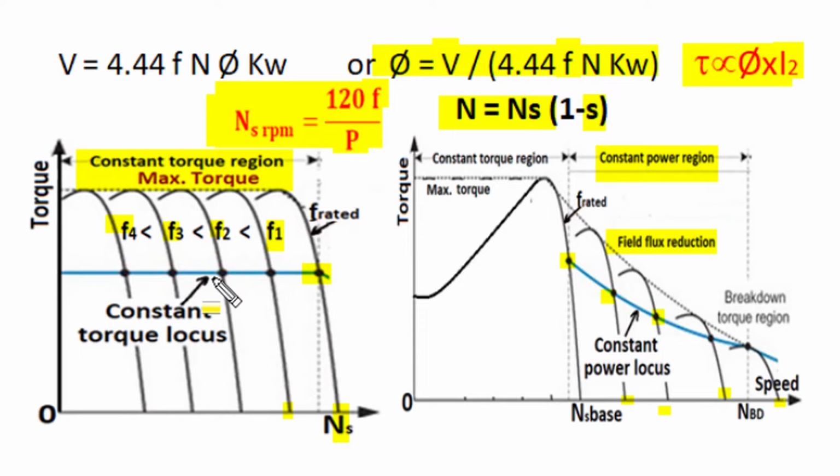So for speed reduction, when frequency is reduced, the terminal voltage of the stator also gets reduced and the V/F ratio is maintained constant, and this control is known as constant torque region control. Whereas for increased frequency operation, we maintain constant voltage and the motor maintains constant power characteristic, and a load having constant power characteristic can have an increased speed operation by increasing the frequency of supply.